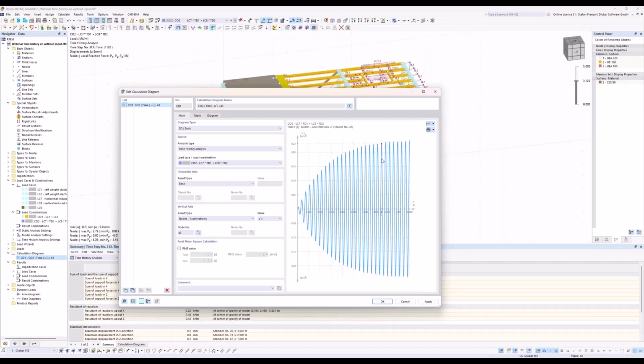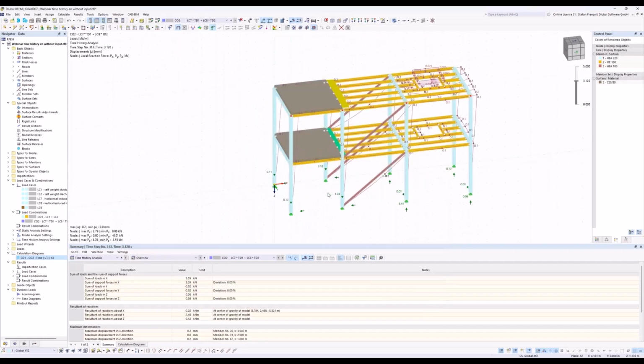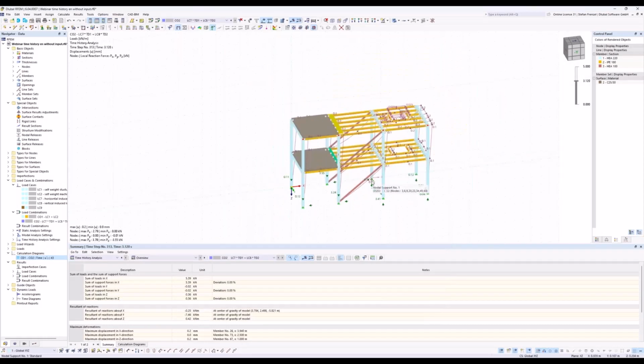That's of course a high value, and that could be now that, of course, also by using the damping, it's not sufficient for us for using the whole building like this. And now we come to the point where we have to optimize normally the structure. So one optimization could be we use another machine, because if we have another induced vibration, then maybe it could work. But normally, it's also possible to change something in the structure.